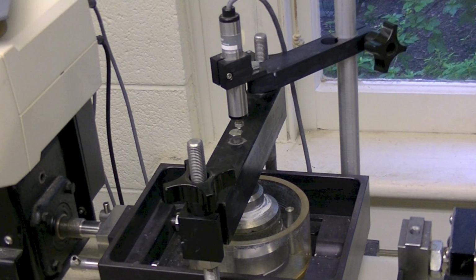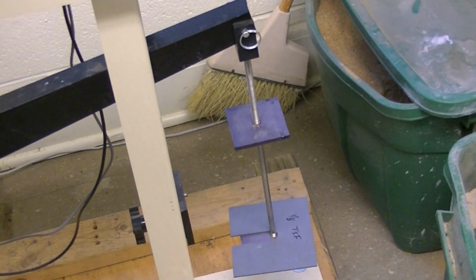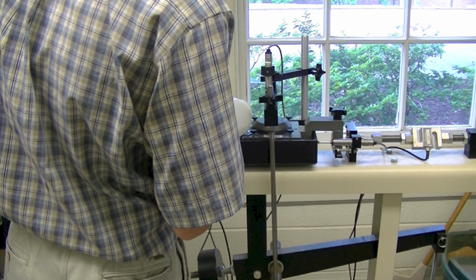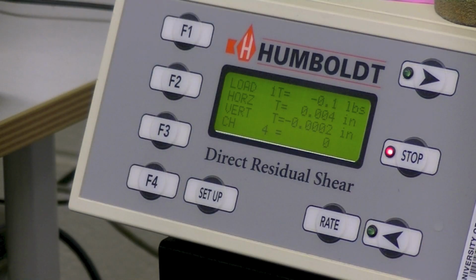Set the start condition so that the readings will begin right when the first load is placed on the carriage. Place the first load on the carriage at the same time the clock starts. Add enough water to the cup to fill the sample completely. Dial readings will be recorded at this time.